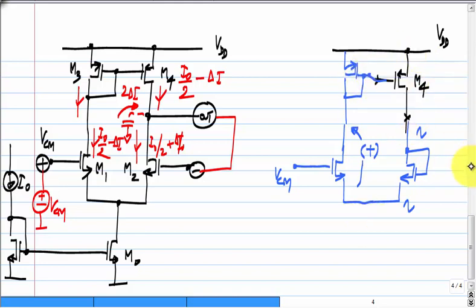So, every transistor is in negative feedback. That is what I am trying to say. Earlier we thought about how to bias transistors, and we saw that we needed certain kinds of gains between certain terminals of the transistors for it to be negative feedback and get biased stably. Now, we made an op amp and put the op amp in negative feedback, but it necessarily implies that all the transistors in the op amp, if you take them individually, will each be in negative feedback, so that it is biased stably.